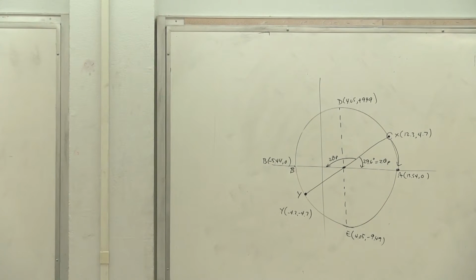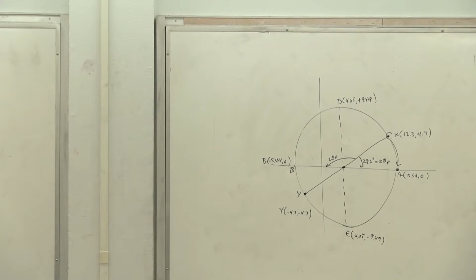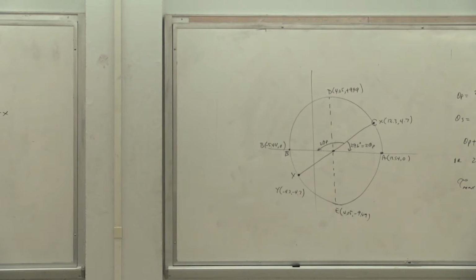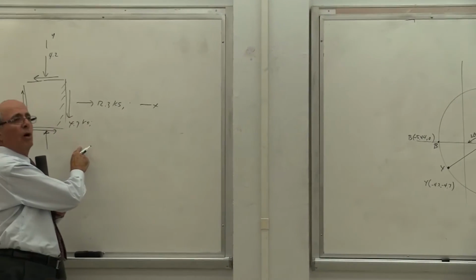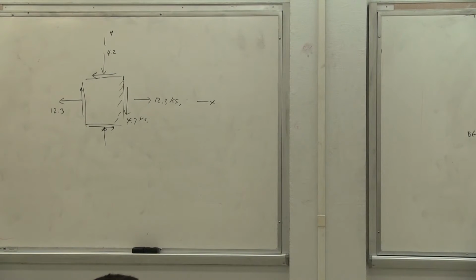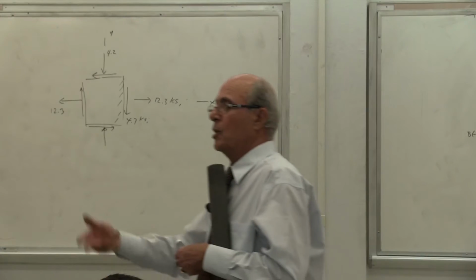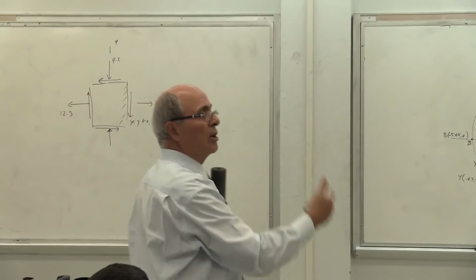Everybody understand that. So if this is X, which actually is not a point, this is the direction. Everybody says, oh, we call it an axis. That represents the surface perpendicular to the x-axis, which has one sigma and one tau. No matter what you are designing, there are always two types of stress, sigma and tau. That's it. There are no other stresses. Even if it's temperature or etc., it turns into this. Torsion turns into this. Transverse shear turns into this. Tension, compression due to P, due to M. This is it. One sigma, one tau.